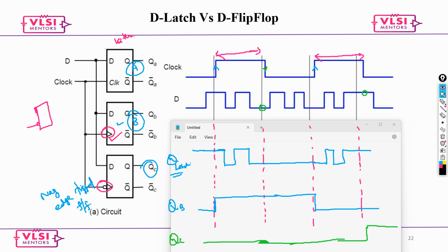In a flip flop, which is edge triggered, at the positive edge we want to see the present value of the data, 0 or 1, at which point it's starting. Based on that, we continue. It will not obtain the same data that we are given. It follows the edge trigger alone. Negative edge flip flop is vice versa. Okay.